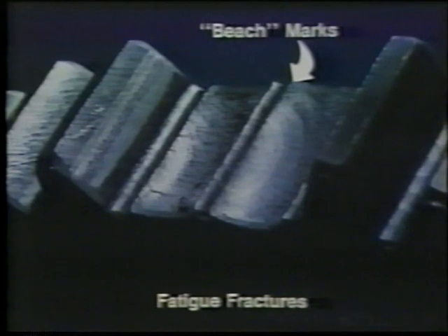Fatigue fractures like these are caused by extremely high stresses on a gear tooth over a period of time. Fatigue fractures are identified by beach marks on the fractured area. These marks are made as the tooth progressively cracks under a load heavy enough to enlarge the crack, but not great enough to break off the entire tooth at one time.